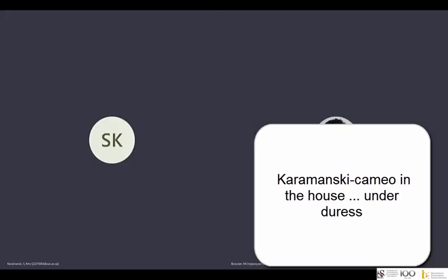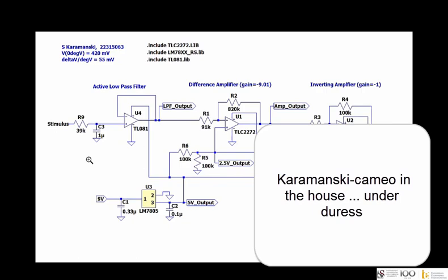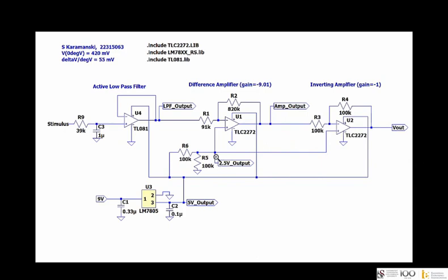E-Design 344 Lecture 5. Okay, so hello everyone. Under popular request, I'm explaining why we're using buffers in our circuits. And basically it's to separate our circuits into different blocks so that we can use the op-amp as a way for the outputs to see a very low impedance. So it almost makes the outputs see like a positive voltage source, and then the input sees an infinite impedance. So what that means is it draws very little current,